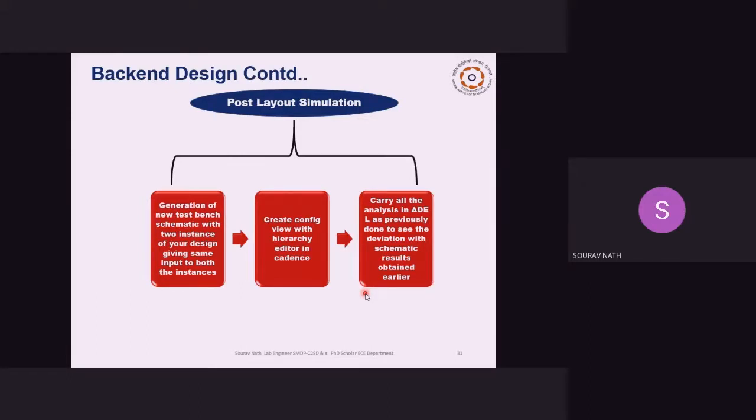Post-layout simulation is basically done by generating a test bench with two instances of your design, giving the same input to both instances, creating a config view with the hierarchy editor in Cadence, and after that carrying out all the analysis in the config view. This is the normal procedure followed in UMC. But due to the shortage of time, I will show another shortcut method for post-layout simulation, which is much easier than these steps. I will show it in this demo.